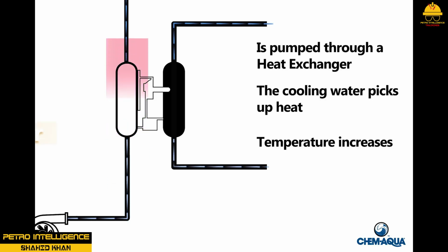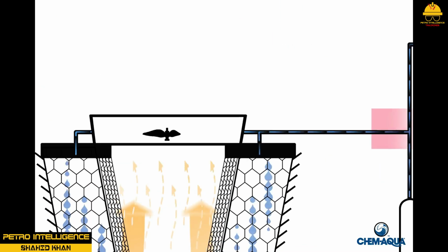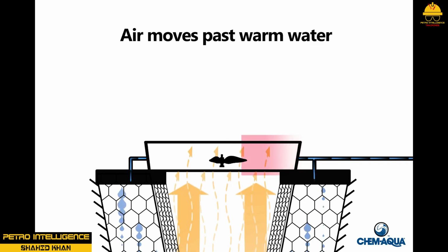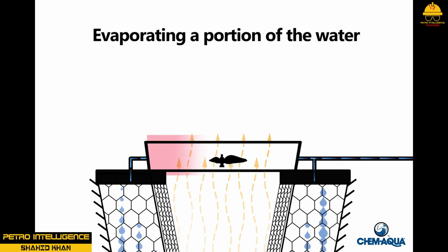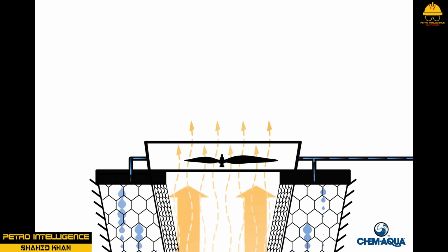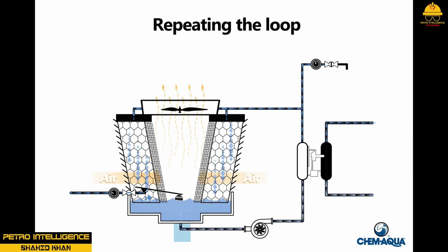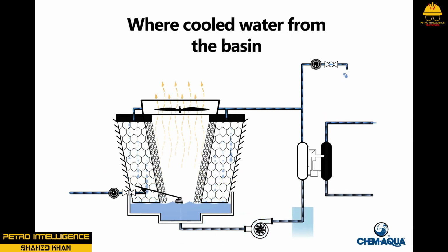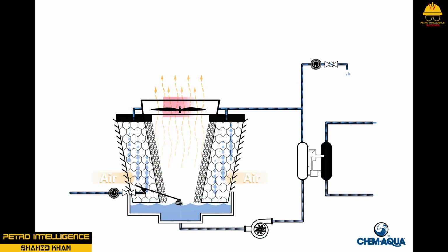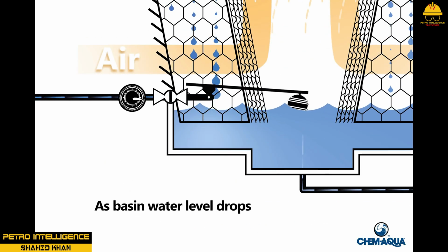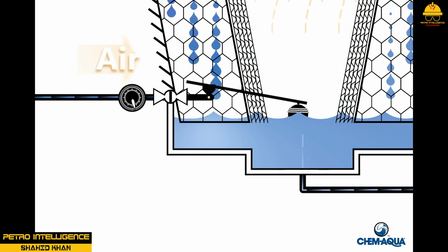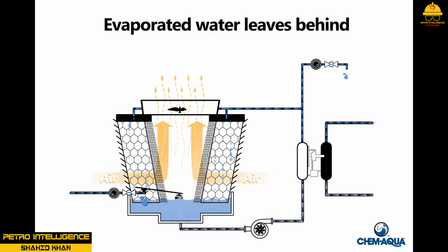As the hot water goes into the top of the cooling tower, it enters a water distribution header, from which it is sprayed over the internal components, the fill, of the tower. As the water falls on the splash bars, cooler air contacts the water. This process removes 10 to 20% of the sensible heat that can be measured by a change in temperature. Another 80 to 90% of the heat energy is removed through evaporation. The cooled water collects in a basin at the foot of the cooling tower, where a recirculation pump sends it back to the heat exchanger.